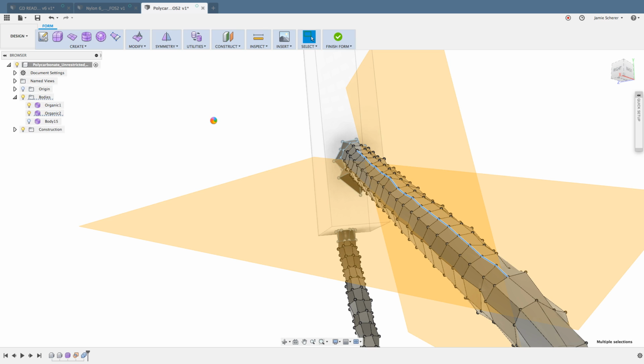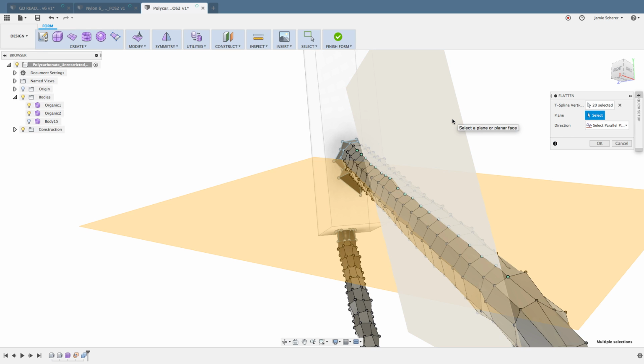You'll see with something like the geometry from the Sculpt environment, it's going to be probably pretty heavy with vertices. So you might see a little bit of a circle spinning pinwheel as it thinks about all those edges, but at any rate, we're ready to go. So by pre-selecting the edge, I don't have to do anything else. But what I'm going to do now is first, I'm going to make sure that all of those edges are flat on this plane, right? I won't assume that they are.